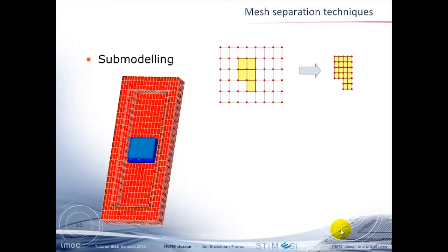This is a case of a kind of old-fashioned bulk micromachined accelerometer in a ceramic package, and we were interested in modeling the effect of mechanical forces on that package and how that feeds through to the performance of the sensor. If you know that this is a piezoresistive device, there are features inside, on the micron scale, which should be meshed at below microns, and the package is 2 centimeters.